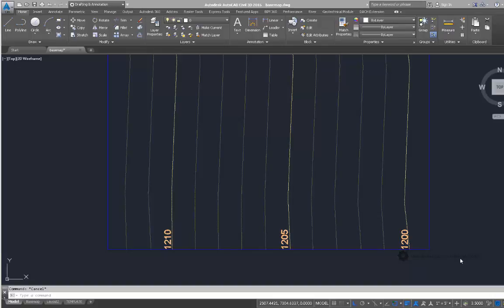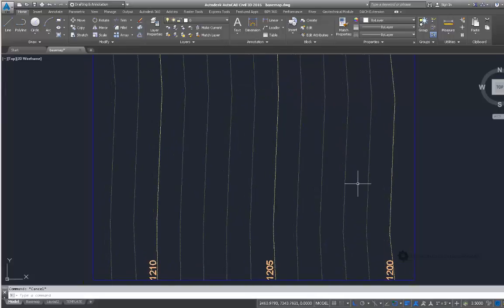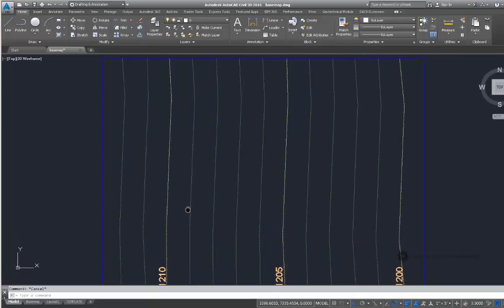So what I've done is I've opened Civil 3D and we have a surveyed site of the same project site, and we need to basically create our design here. We don't have the sidewalk or the gazebo, so we need to sketch that in. But for the purposes of this demonstration, I'm not going to show you how to sketch that in because you should know how to do that by now. We're just going to pretend that there is a path here and focus mostly on how we grade contours in Civil 3D to conform to a specific slope range.